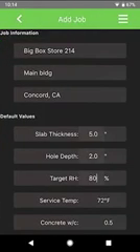In the Add Job screen, you can input job-specific information, such as the name of the job, the structure name, and the address. You can also add information specific to the concrete slab, such as the thickness, sensor hole depth, target RH, service temperature, and concrete mix design water-to-cement ratio.